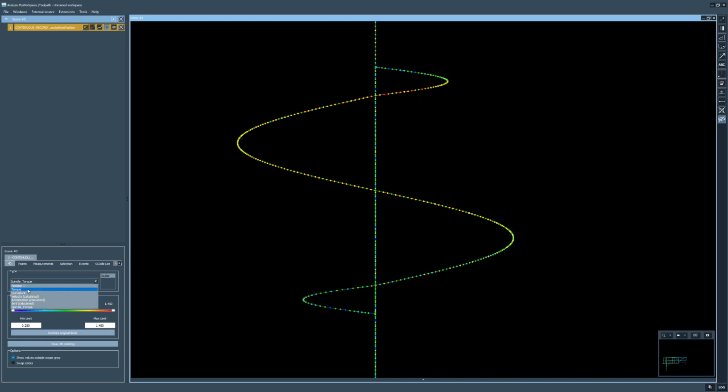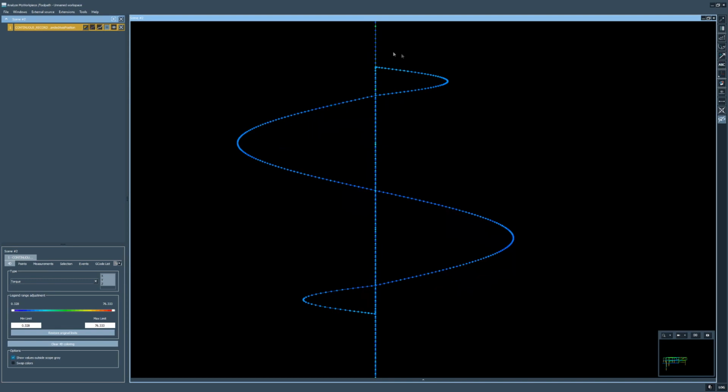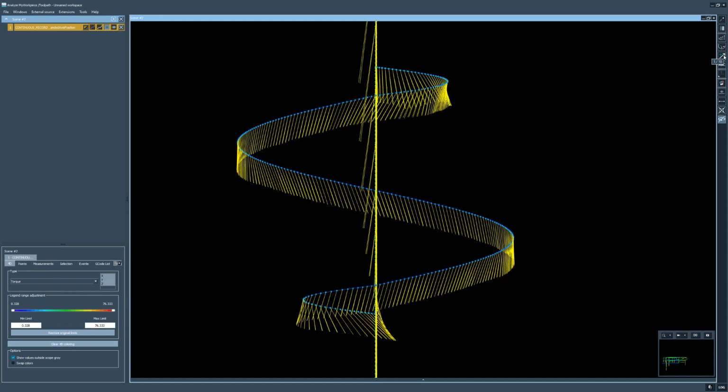And what I can also visualize in this area is the torque of the motors. So I imported torque for X1, Y1, C1, and we now see it looks a little bit different here, this 4D coloring tab. If I select spindle torque, I see scalar. And if I select torque, Toolpath tells me XYZ. And XYZ in this case means, okay, Toolpath understood this is a vectorial data set, and as you remember, we can also visualize this custom vector here. And now we see color-coded the magnitude of this vector.